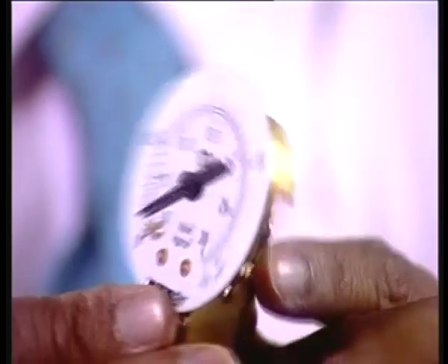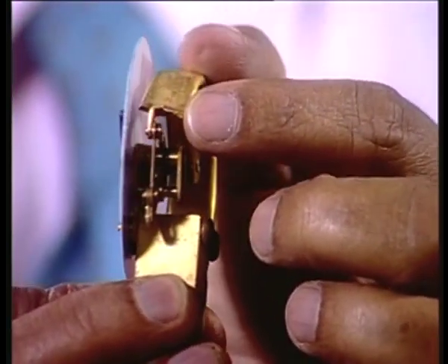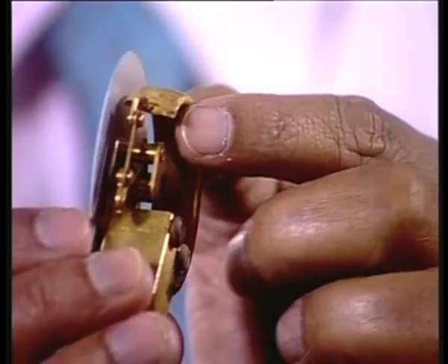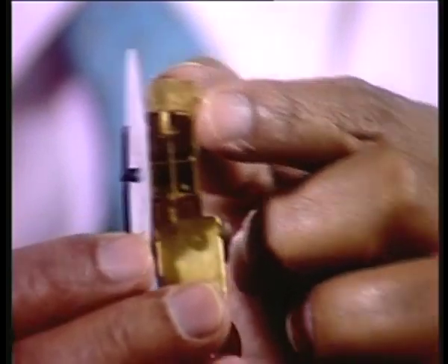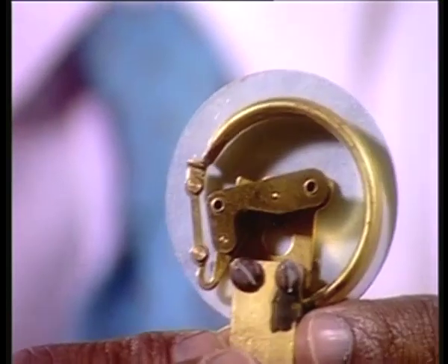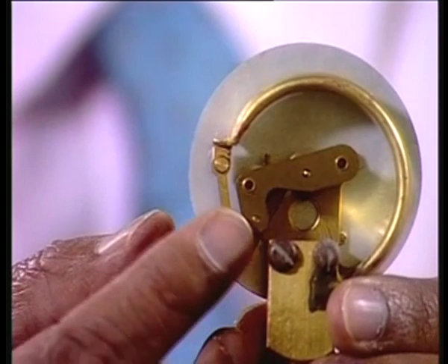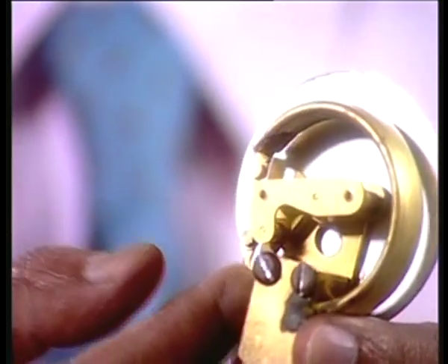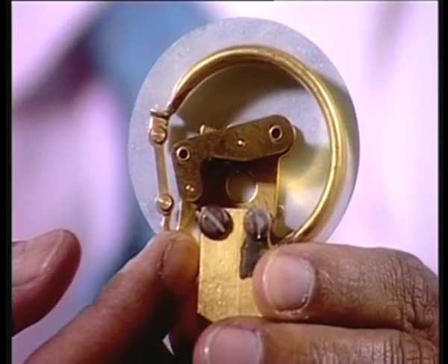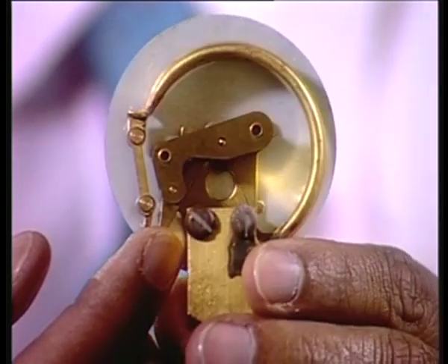But if I increase the pressure, you can see here, this is a closed end, it is sealed here, because this is a typical Bourdon, your C-type material. So you see here, this is the sealed end, right? And here you can see the sector. Again I will show you. You see the sector is moving. You can see the sector. Okay, the sector is moving.